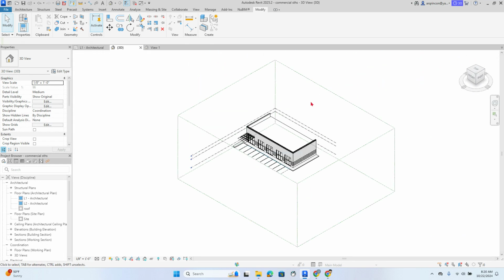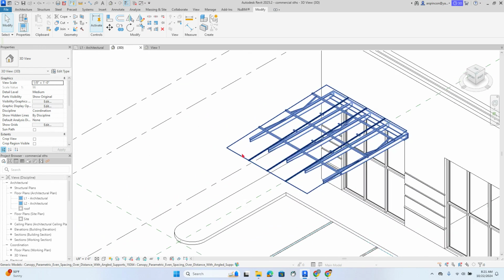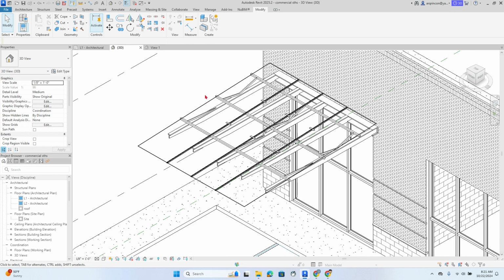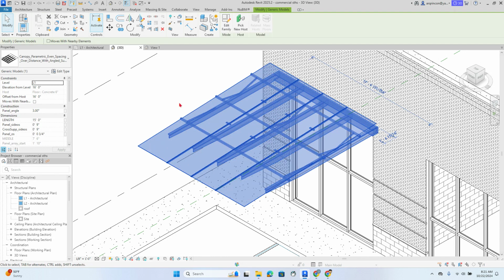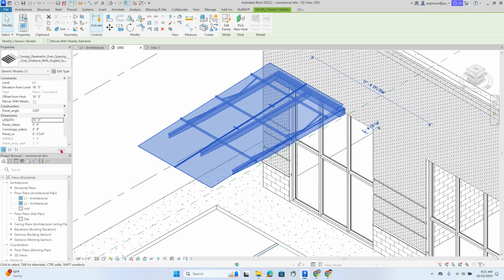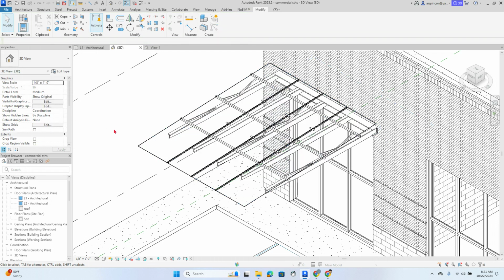Doesn't mean that it's bad. It's just a canopy that we're bringing, right? So we need to go here and select the canopy, and then we can go here on the properties, basic properties like the length. This one says 15. Let's see what kind of length is used here. Let me change it to, I don't know, 10 feet, and then apply that change, and that's the length that they're talking about here. Okay, so my length of 15 is perfectly fine, right?